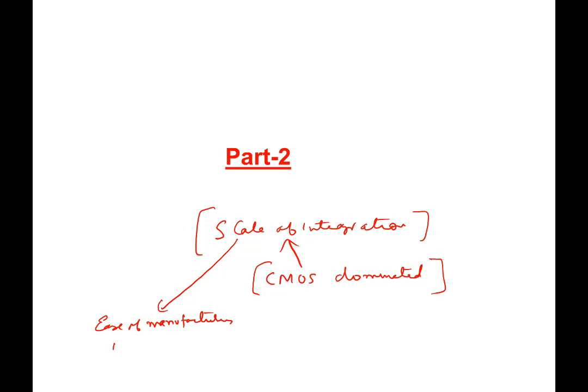And the other one is power dissipation. I'll not go into the details, we don't have CMOS-like bipolar circuits. Bipolar circuits, most of them that we have, will consume power under standby condition. When you have a logic 1 or a logic 0 or whatever, they'll consume power.